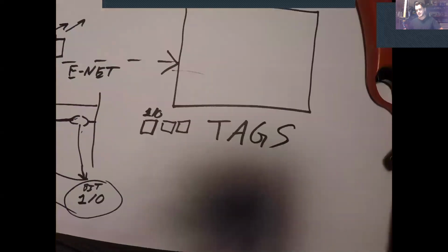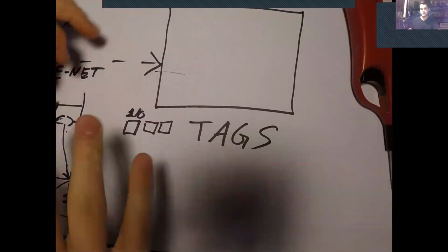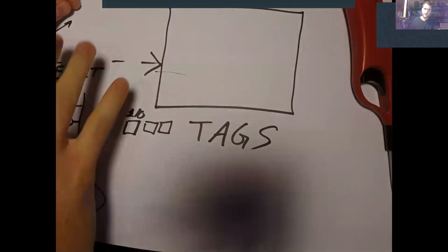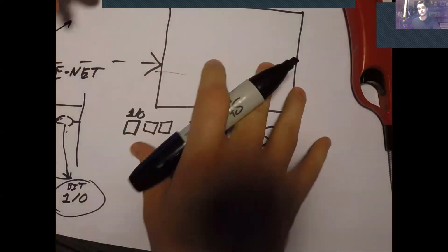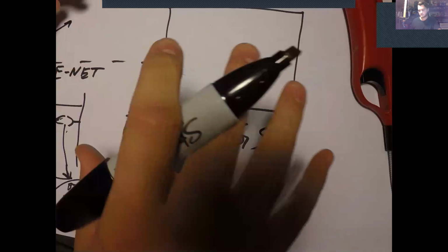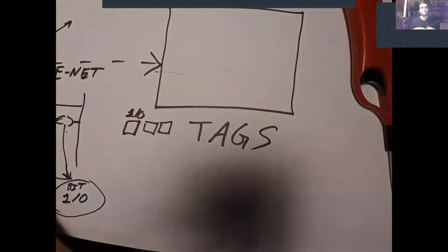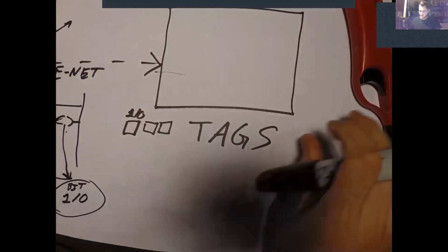Okay, and what that looks like is, generally speaking, we're going to start defining these in the PLC and then migrate them into the HMI. You can do that either direction. You could define them in the HMI first and then go define them in the PLC. But generally speaking, it's usually easier to start on the PLC side because you have a specific use for it, or a specific function that you're using it for. And so it makes more sense to define it there and then go over and define it in the HMI.